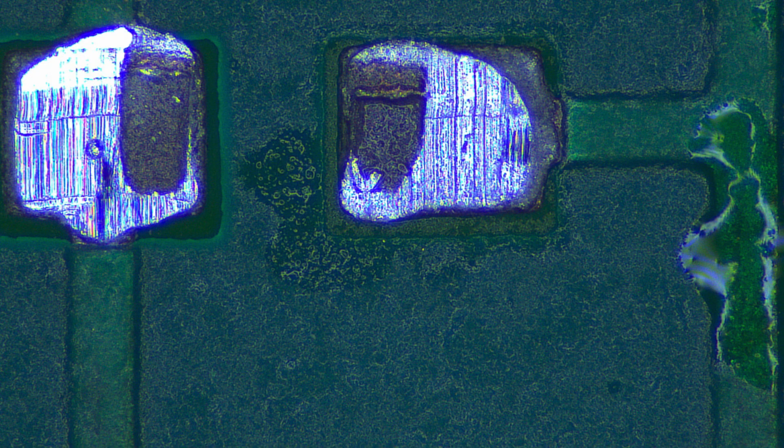Let's walk through the mechanism. First, you have residues on the surface of the assembly. These can come from flux, cleaning processes, handling, or the materials themselves. Those residues often contain ionic species. Now, introduce moisture, which is almost always present in the real environment, and finally apply a voltage bias. This combination of residues, moisture, and bias creates a system that is no longer stable, and at that point, several failure mechanisms can begin. Electrochemical migration, which leads to dendritic growth between conductors, leakage currents, and corrosion.